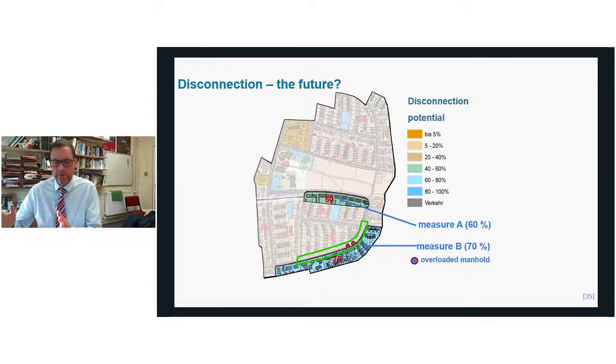So getting those combined pipes, removing the surface water inputs to them, and creating basically a new surface water pipe network that would convey those flows to watercourses. But I think now it's recognised that although that's still the solution in some places, often that's not a solution, because you just end up with all those pollution flow problems in the river.